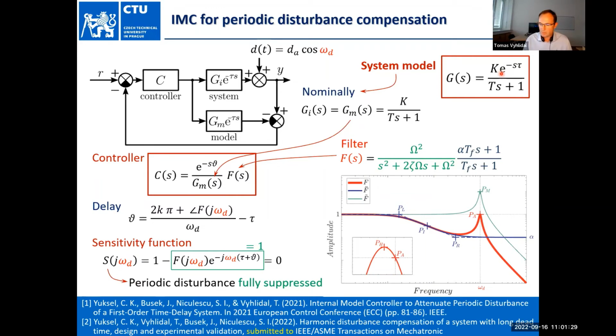from analysis of the measurement data. So what we do, we apply classical synthesis based on dynamics inversion, employing an additional filter in the controller and an additional delay. The filter is structured to gain the feasibility of the control implementation, and also to achieve the pointwise vibration suppression at the point omega d.